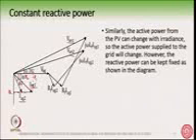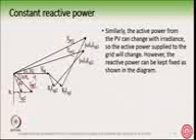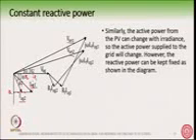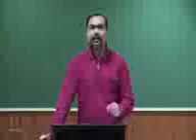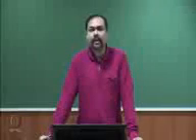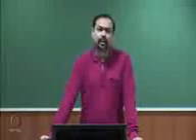Okay, so when can we have this for the same PV converter? It can happen when the irradiance from the sun is changing. So the power output from the PV converter is changing, and so the P will change, but we may ask the converter to produce the same Q as before. Of course, you can have both changing P and changing Q, and accordingly the VAN voltage will be adjusted with respect to the grid.